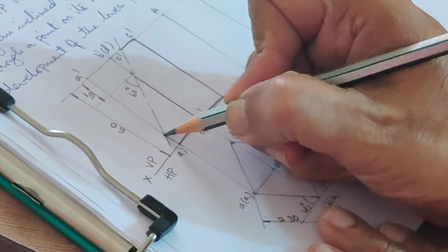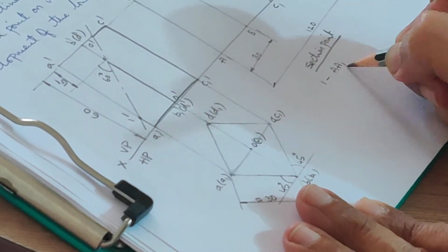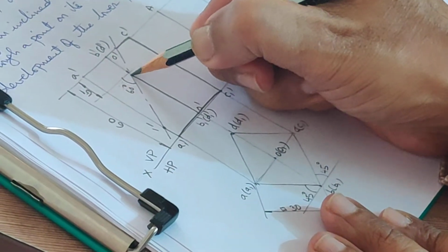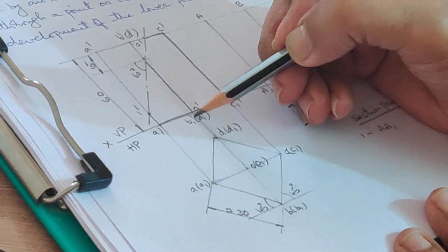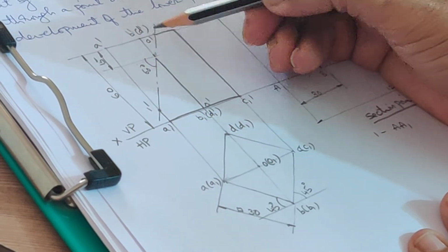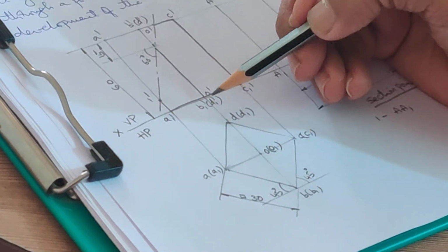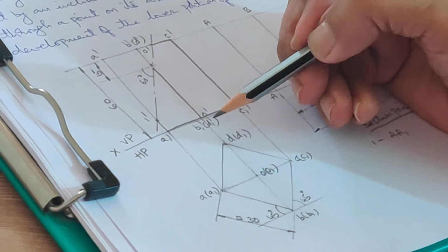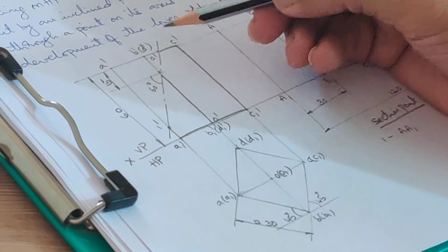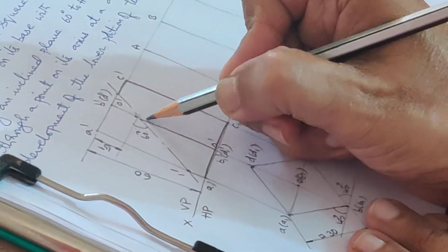Okay, let me start from this end, 1 dash. So point 1 is on the longer edge AA1. Next, come here. You have three edges in fact there: one is BB1, the other is axis, and the last one is DD1. Axis we do not name any point, but we have to name the points on both the longer edges BB1 and DD1. Among these two, BB1 is visible, DD1 is invisible. You have to put them in brackets. So I'll start with 2 dash, 2 on BB1.